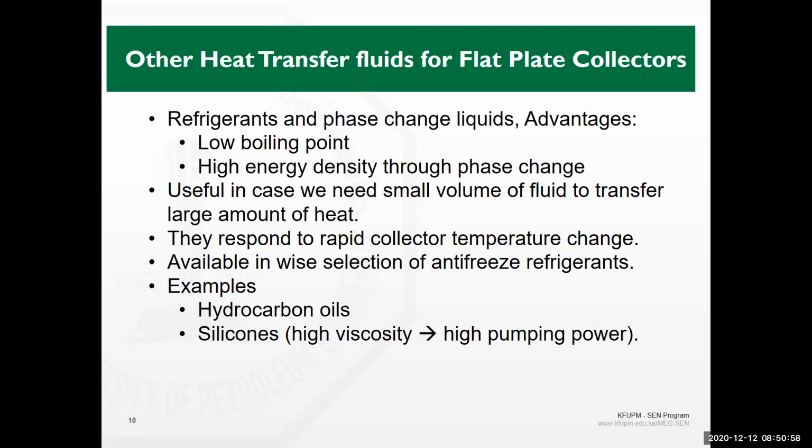So basically we had to use paraffin wax, and the wax was below the absorbing unit or the absorbing surface, the absorber of the solar plate. So we have air passing on top of it and wax at the bottom. What would happen? As the solar energy is there throughout the day, it heats air in the solar collector, and definitely first it heats the absorber surface.